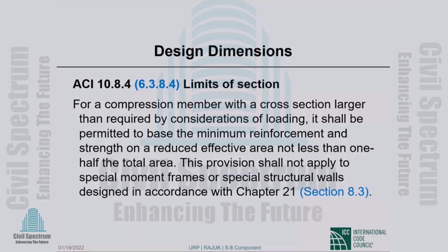prohibitive. The formwork gets very complicated. I do not know if you realize formwork which does not stay in place beyond 3 or 4 weeks costs typically at least half the cost of a concrete structure.